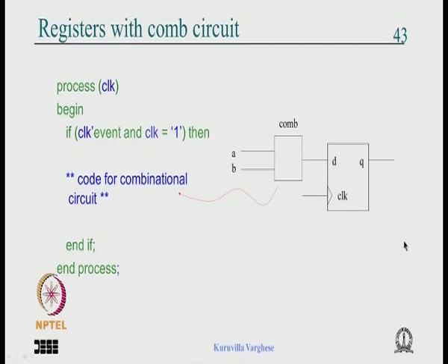You simulate that, and for whatever reason you may not verify what actual circuit you have got out of it. You go into simulation, you will find that the decoded output comes with a delay, and then you do some adjustment to counter that delay. Okay. And you can end up in real soup with that, and that is dangerous.